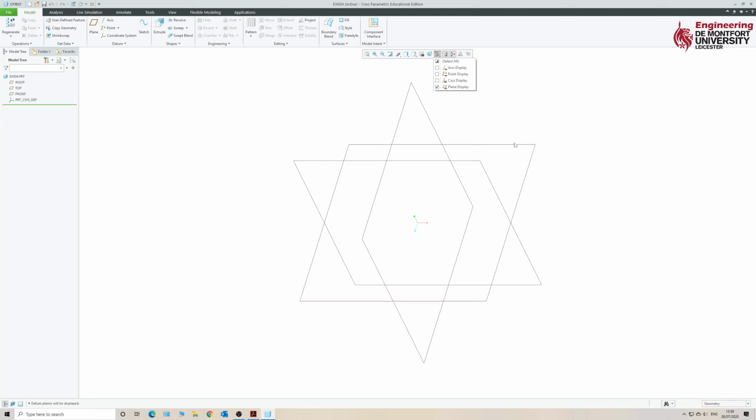And the first thing we're going to do is set the sweep path. So it's a little bit different to what we've done before. The sweep tool is basically an extension of the extrusion tool. Extrusions will always generate a solid perpendicular to the sketch, whereas the sweep tool will extrude along a specified path. Okay, so this is quite helpful when we're generating things like tubing. So in order to do this, we can sketch our path first. So we first need to select a plane. So we're going to click top, and then we're going to click sketch.